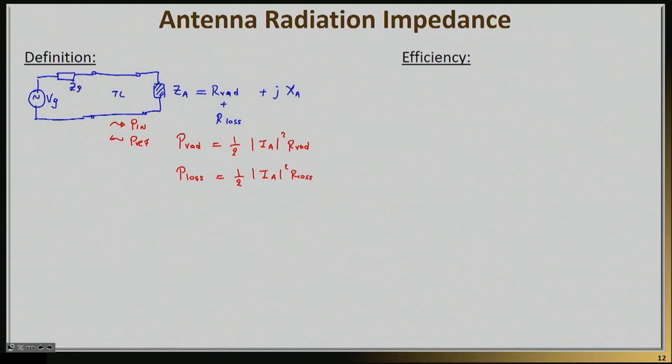It's actually this first equation that you will see here that basically forms the definition of the radiation resistance. So in other words, the radiation resistance is essentially a fictitious resistance that would have consumed the same amount of power that the antenna is radiating. So the radiation resistance has units that are definitely ohms. And most people, when they talk about the radiation resistance, calculate it exactly by this equation that you will see here. Similarly, the effective losses of the antenna that are related to the efficiency we were discussing in a previous lecture are essentially given by this equation here.